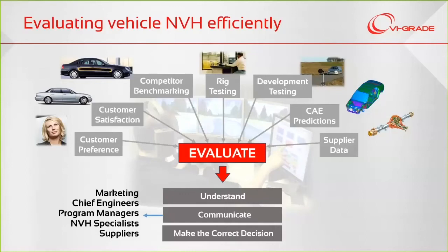That's really important because, as an example, with CAE data, you can generate sounds in lots of different CAE packages. Let's just take, for example, the sound of the exhaust. Simulating exhaust noise is a pretty robust technology now, pretty mature. So you can generate the sound of the engine at the exhaust pipe during a run-up. The problem with that is that even though that's very accurate and very believable, nobody listens to the sound of their exhaust pipe as they're driving the car, accelerating away at second gear wide open throttle.